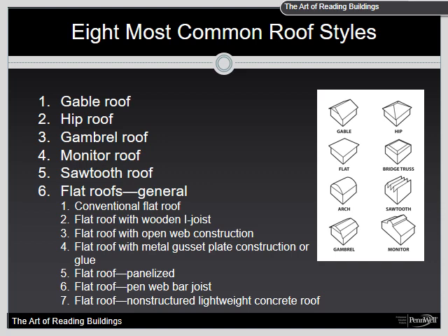Flat roof panelized. This roof is only found west of the Mississippi and is the most predominant on the west coast, where wood was plentiful, and is commonly found on wood, masonry, or concrete tilt-up slab buildings. However, due to the rising cost of wood, this roof is being replaced with steel open web bar joist roofs. There are two panelized roof systems, all wood and hybrid steel.